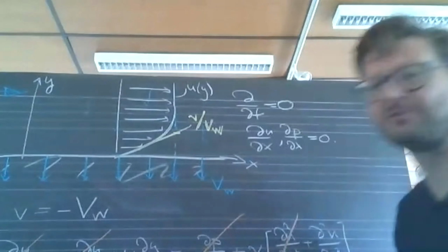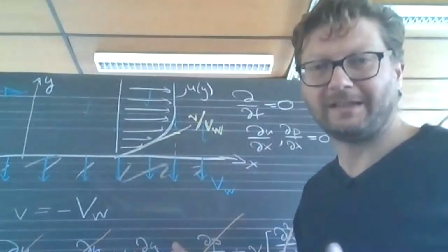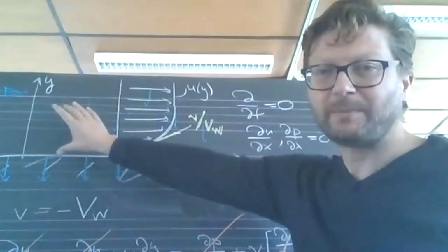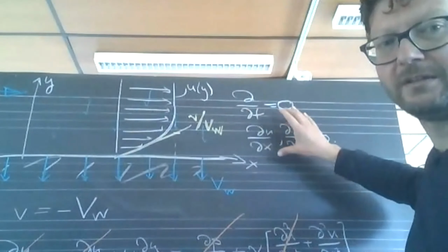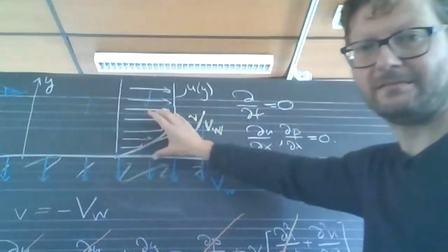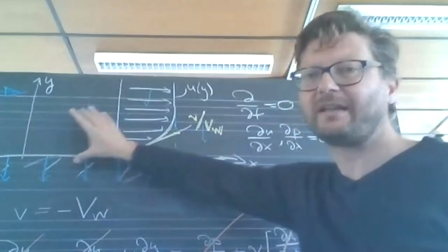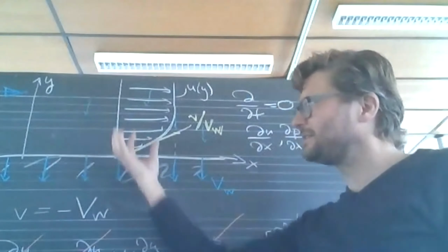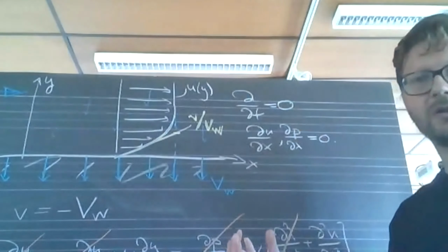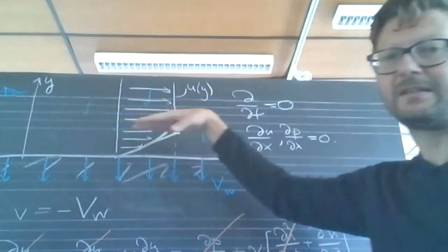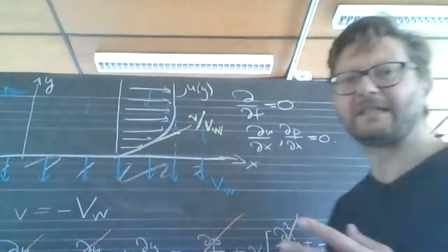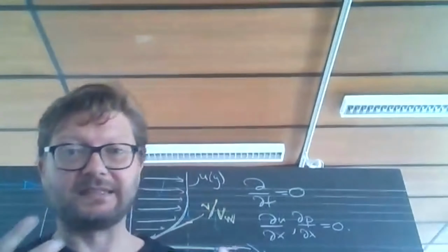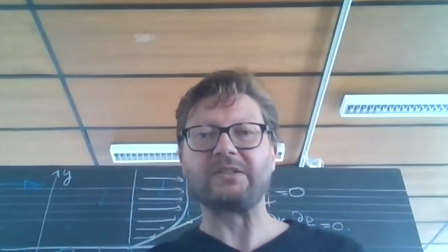This is a very special boundary layer. First of all, it has a really simple solution, just an exponential. And second, it's one of these boundary layers that is not getting thicker with x. The classical Blasius boundary layer is always thickening more and more. Because we're continuously sucking out fluid through the wall, we can maintain a constant thickness. In addition, and that's something we will talk about in lecture number 9, this is a boundary layer which happens to be very, very stable.